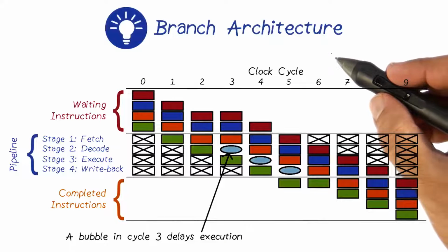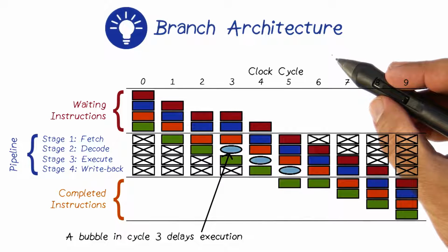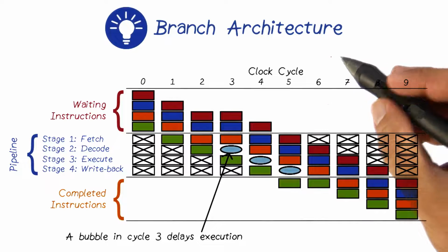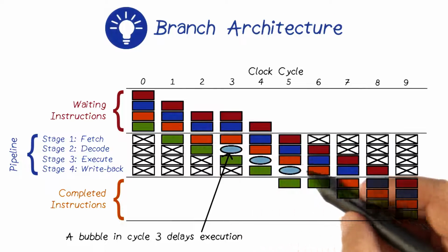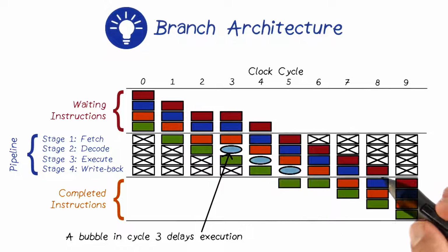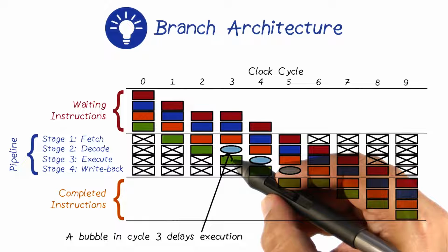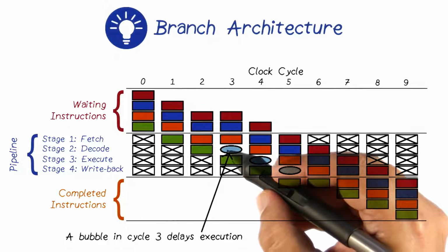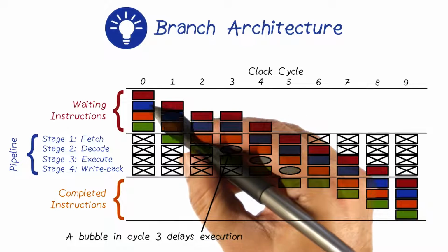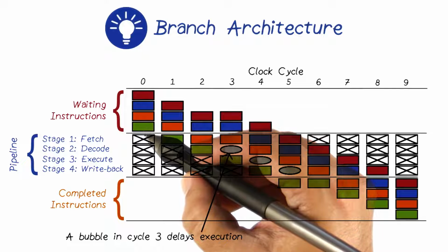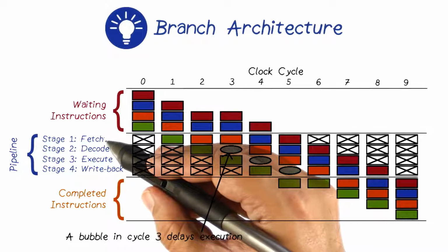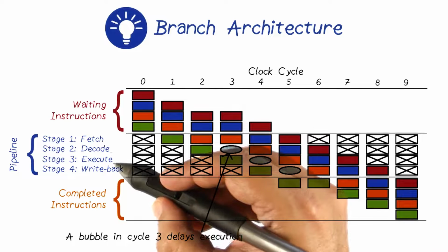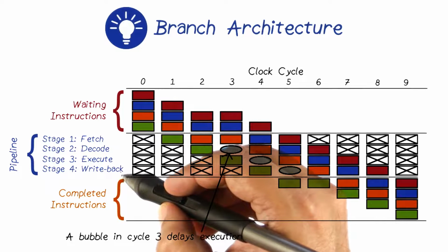Now let us recall what is the problem with the branches. Branches are of course great for implementing control flow. They allow the program to execute in different ways on different inputs. But what happens during the execution of the branches, as you can see through this simple pipeline example, is that it results in a bubble. In other words, each of these instructions is going through multiple stages. Typically, the instruction is fetched, then it is decoded, then it is executed, and then we have a write back.